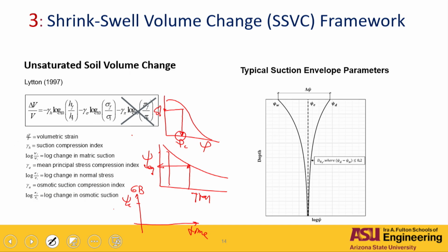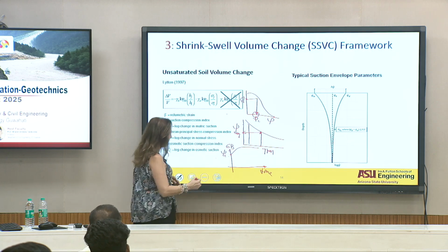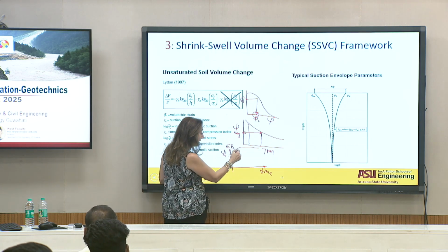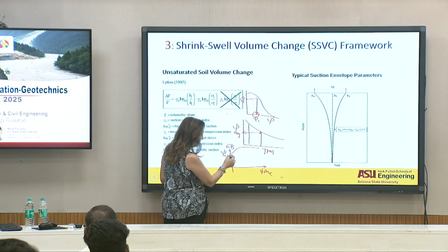So that's your compaction condition, I'm sorry, and because it's Arizona, it's going to be tending to a much higher suction value. So the equilibrium condition is going to be here. And it's a granular base, it might take a few days to reach, right, if there is no rain and the evaporation keeps going. But it might happen that during that time, you got a lot of rain.